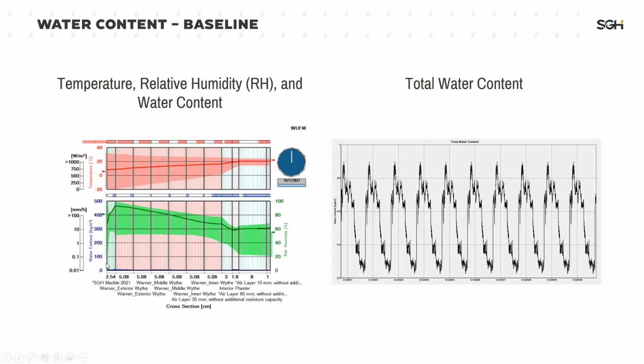The relative humidity, you can see here in green, it fluctuates highly right on the outboard layer of the marble, but not much is absorbed by the marble. The vast majority of our relative humidity gets trapped around where that water source is between the marble and the brick layers, right here. We generally say that relative humidity that's above 95% would be cause for concern, and there's a risk of condensation in that layer.